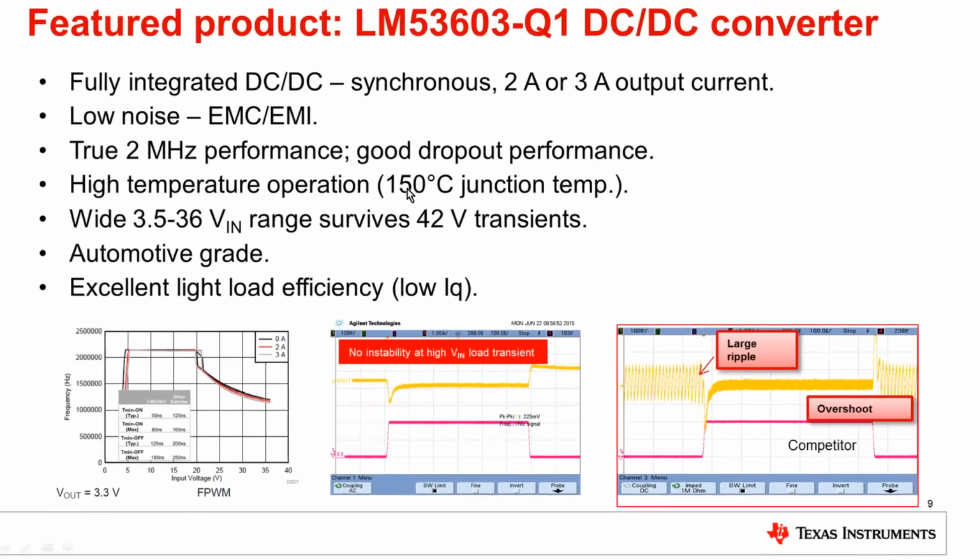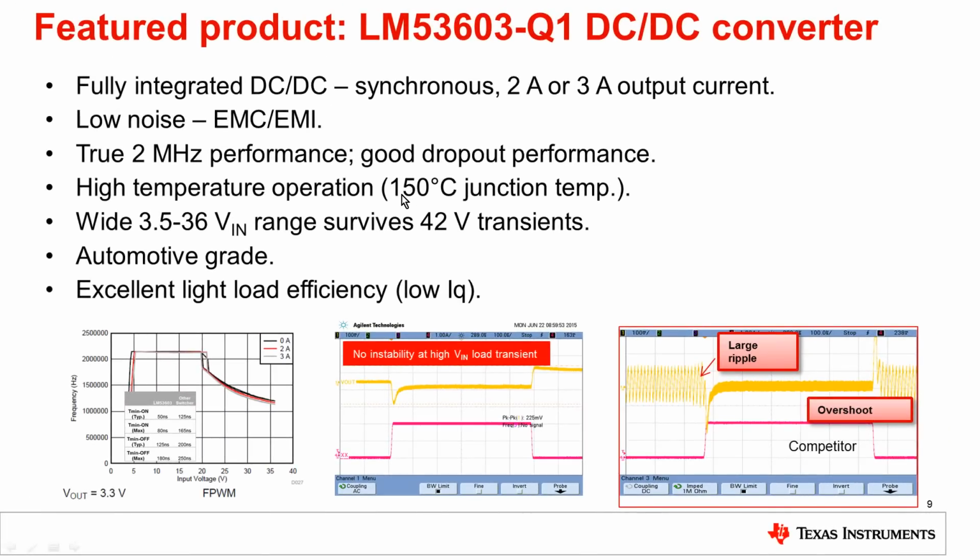Also, this particular device supports up to 150 degrees C junction temperature, and also has excellent light load efficiency and an IQ in the range of 20 microamps.